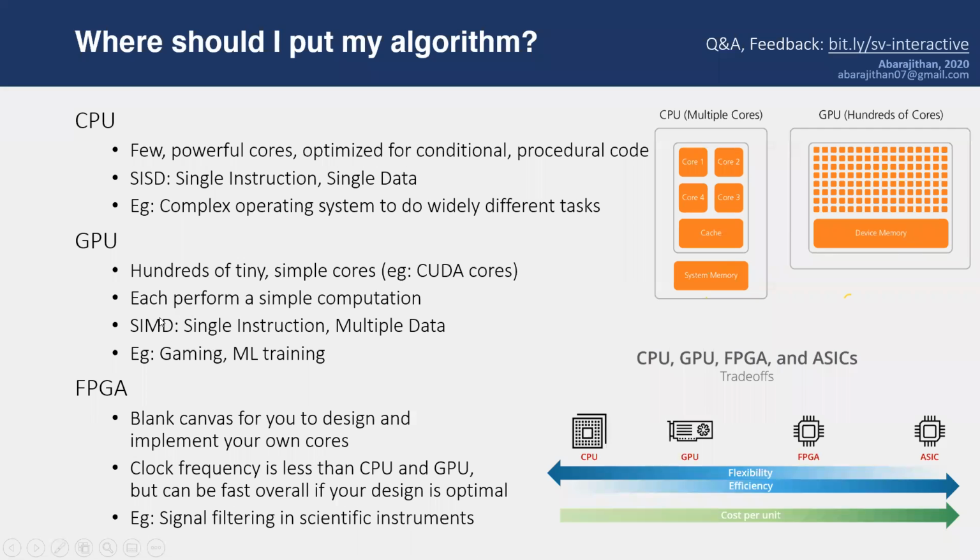The driver software takes multiple of these cores and programs them this way: single instruction, multiple data. So most of them will be doing the same thing, but on different data. This is very useful when you want to do video encoding or gaming or something.